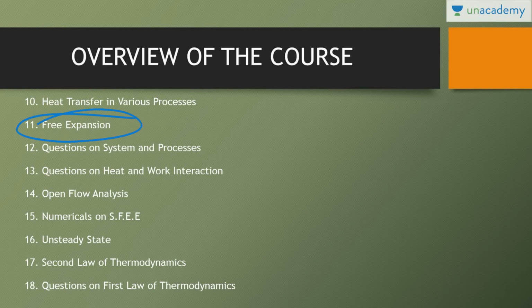What is free expansion? What are the effects of free expansion? What are the different results of free expansion? That is, work transfer is equal to 0, final temperature is equal to initial temperature, final internal energy is equal to initial internal energy. Lesson number 12 is questions on system and processes.